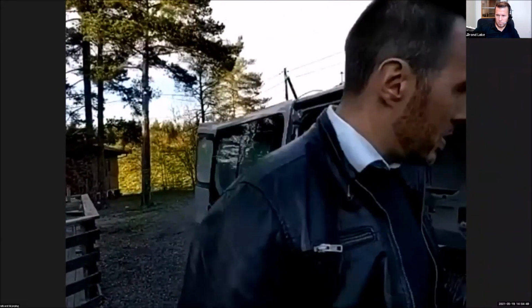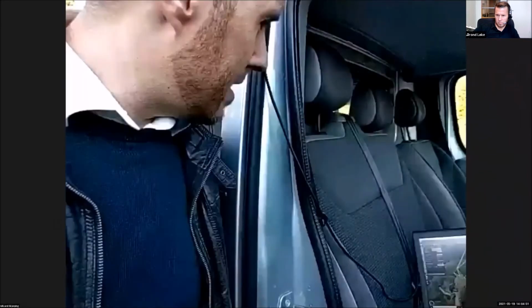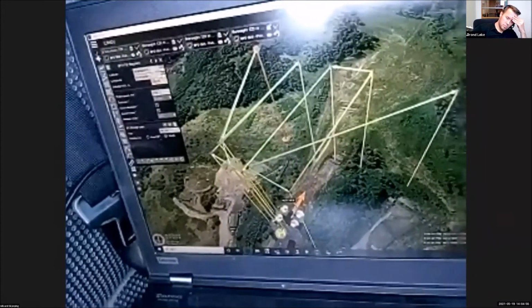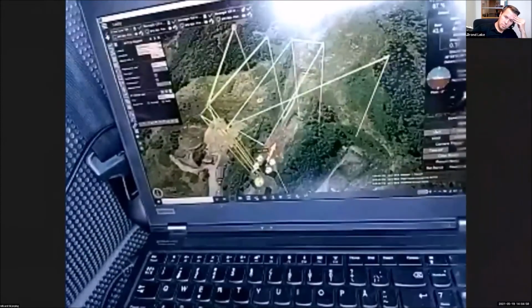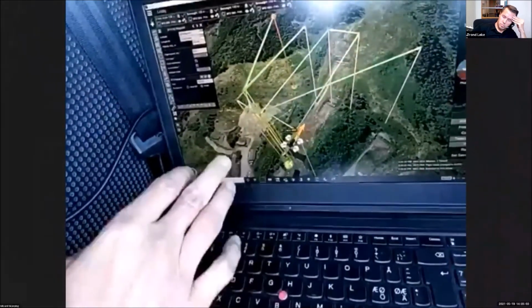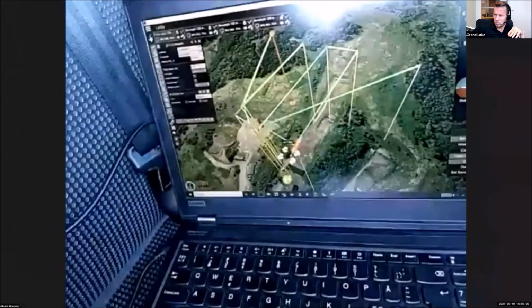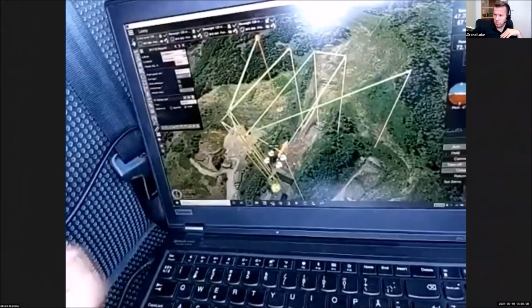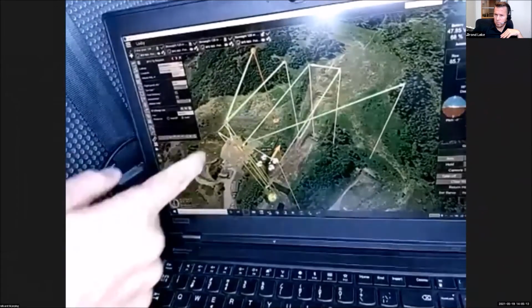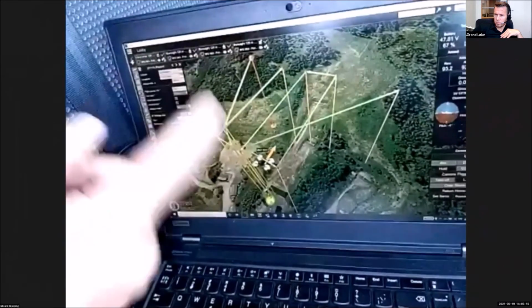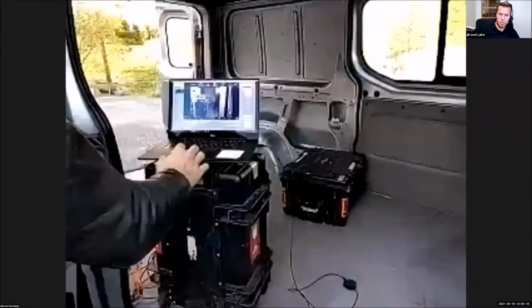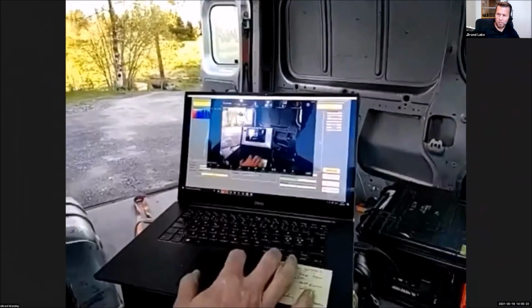So you can watch here the flight plan in the DCS flight planning software. You can see the drone is moving here. What it's going to do first is a quick alignment of the navigation system, so you get good INS accuracies. And then we're going to fly 3 parallel flight lines, which we're going to process afterwards. Then it will stop with also an alignment before we land. This is like I mentioned yesterday, to get the INS solution good very fast.